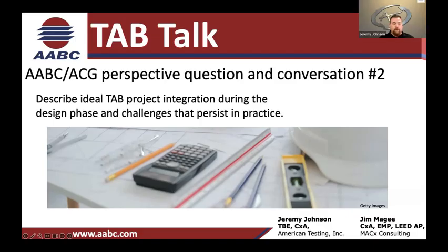Or every once in a while you might see some dampers installed in a medium pressure VAV system, and you're like, why are these dampers here? These dampers are going to cause more problems than good. Delete them, get them out, don't need them, right? So this is what you're going to look for in the design phase, if someone lets you.